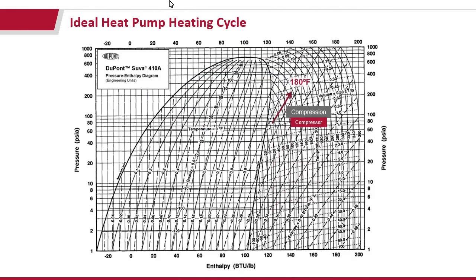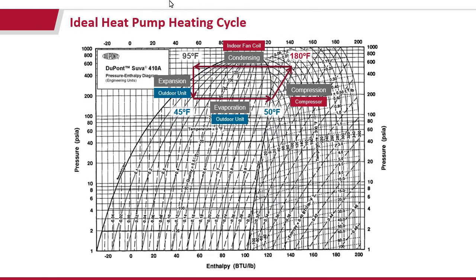So then we have the opposite, which you achieve with a reversing valve in one of these systems. It's already in the system. You don't have to worry about trying to add that. It's just in there. And you've switched it now where your indoor fan coils is where the condensing is happening and evaporation is happening outside. So just basic refrigeration cycles, but good to keep in mind because these are the fundamentals of how these systems function.